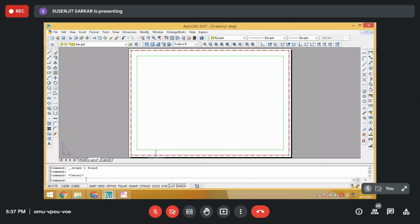To do this, I have to go to explode. This is the explode command because it comes under modification. I have drawn the rectangle and then I want to explode it, so it comes under modification. That you have to understand. You can select this command from here or you can write explode in the command line. It will ask for the object to explode. Obviously, I'm selecting this one. Then press the right mouse button to confirm it. When I press the right mouse button, you can see the lines are actually exploded.